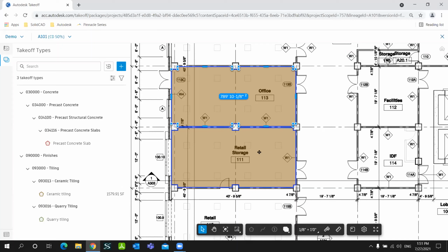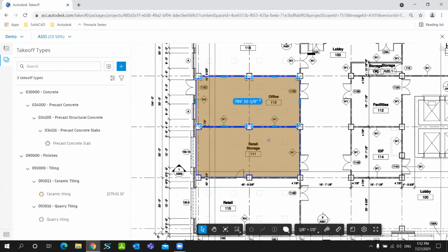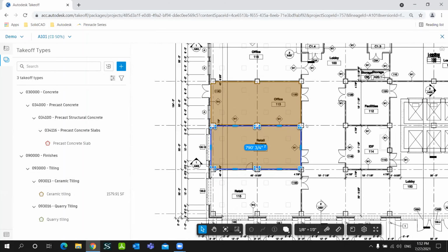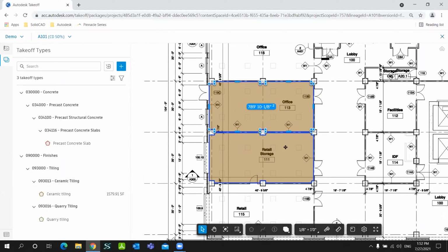So now when you select, you cannot select both. So I'm going to combine. I just want to show you the combine feature. It's the same thing, but the thing is, I don't want to select every single takeoff. So I want to do one selection. So here I select one and hold Control, select the other one, and click combine. So when I combine them, it's just now one selection with the total seen here.